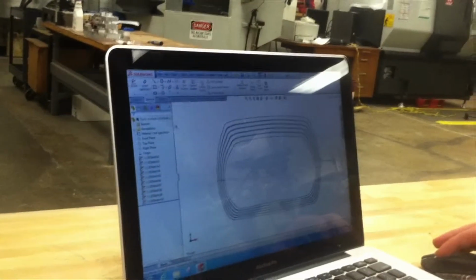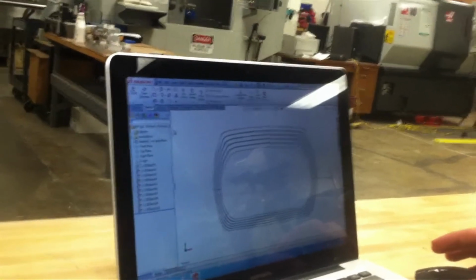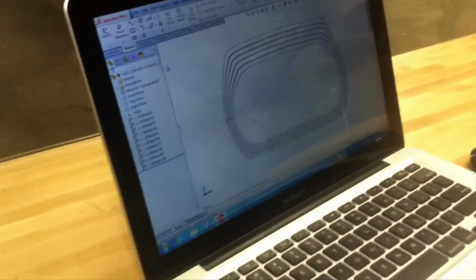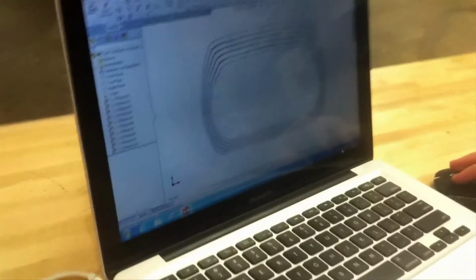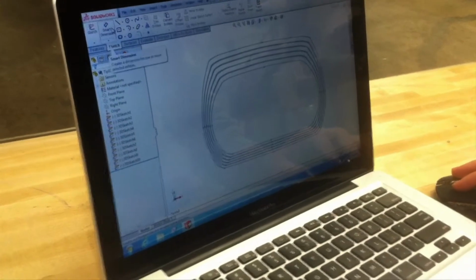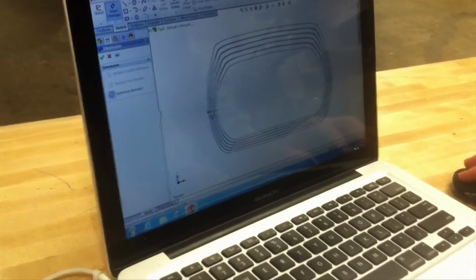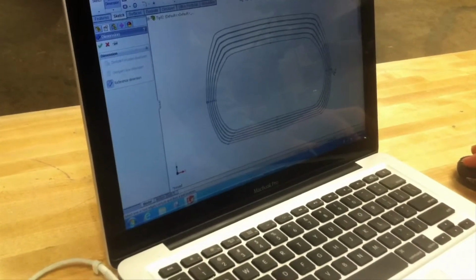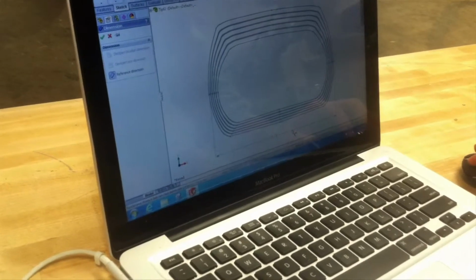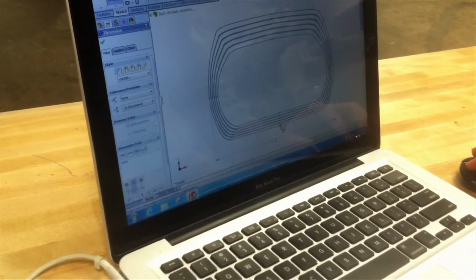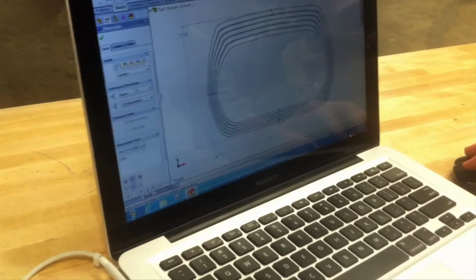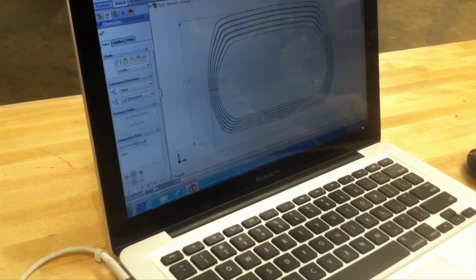software. Alright? Yep. Alright. So here's just a helpful tip for cutting out the foam and to make sure that the sizing is right here and then in the routing software. So when I have all the DXFs, I go normal to it. And I use the Smart Dimension tool, and I go to the outer points here, just to get a rough measurement. So that's 11 inches that way, and this way is 7.15.